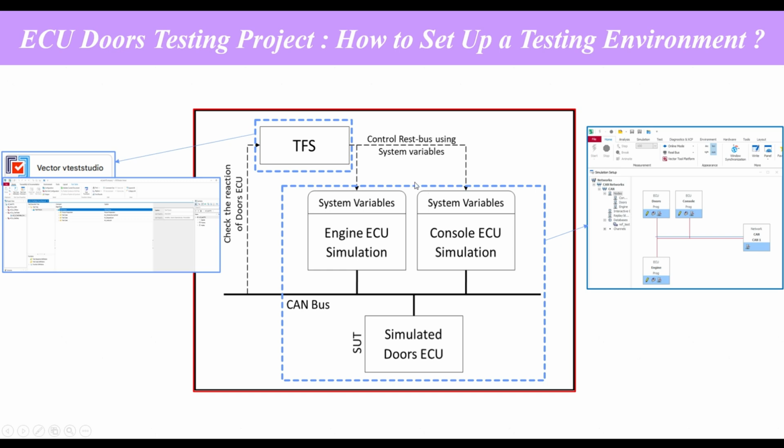Here you see the two interactions between the CAN bus and vTestStudio, our test framework system. The TFS can check the reaction of the doors ECU, and it can also control the rest bus using system variables, the system variables of the engine ECU and console ECU.